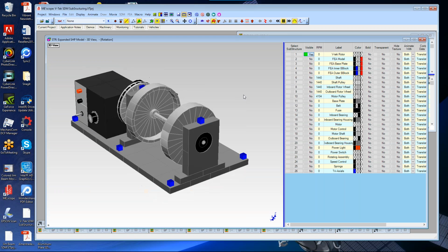Now, if I animate ODS data, which is typically order-related ODS data, the parts will rotate at the same frequency. They'll complete one cycle of rotation as the animation if I'm looking at the first order ODS data. So if I go to second order, then the second order data will animate twice as fast as the rotation and so forth.